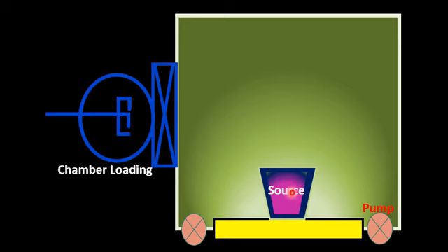Also please note that it's not necessary that MBE uses one source material at a time. Let's say if we want to deposit gallium aluminum arsenide, there is a possibility that the MBE reaction chamber has a gallium container having a gallium source material, another container having an aluminium source material, and a third container having an arsenic source material in solid powder form.